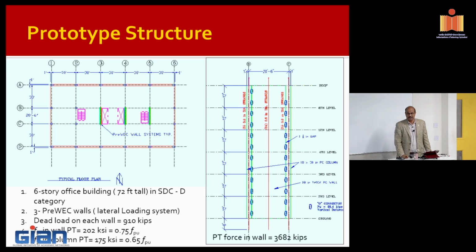In the test that we conducted under quasi-static, what we mostly got was the equivalent damping coming from that alone, an 18%, is what the committee was asking. The question was, which one is it? You said the hysteretic damping is predominantly the material damping, which is displacement based, right? They have to be displaced to plastify, whether it could be reinforcement or this connector. So all of those things are displacement dependent.